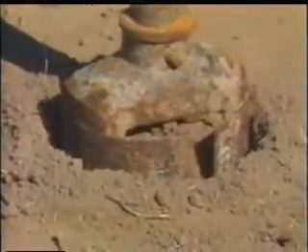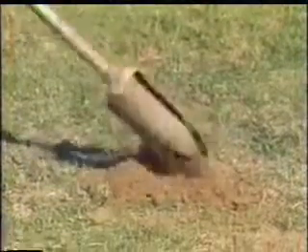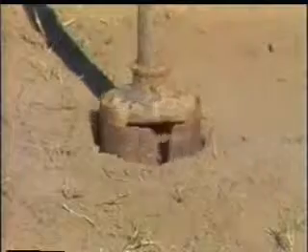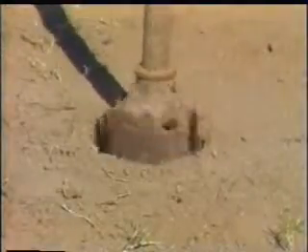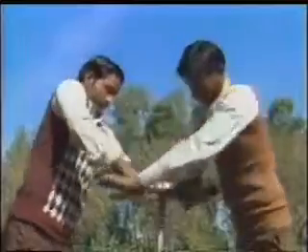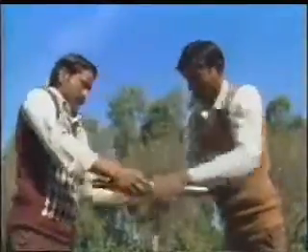When it has penetrated through its length, it is then pulled out. The soil retained in it is removed for inspection and is deposited nearby. Auger is inserted in the hole again and the process is repeated until the bore hole up to desired depth is made.